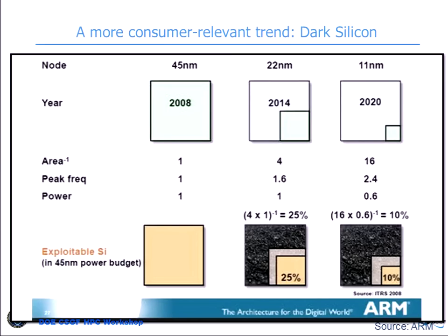The other thing that's driving power, and this is an entirely different trend, is your cell phone. This is Moore's Law coming together. This is looking at a slide from ARM that illustrates it perfectly. It's called dark silicon. When you look at the process for developing semiconductors today, Moore's Law is going to continue. We're going to have more transistors that we can put on a chip. That's not a big problem. The problem is that, and this top graphic illustrates the amount of area that this same functionality would take up in a chip in 2020. It would be 1/16 of that chip.